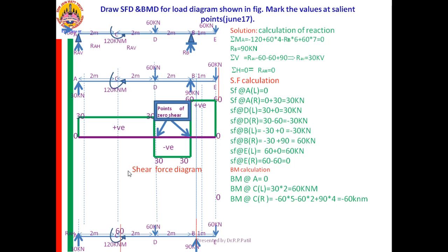Okay, bending moment at D I want. As far as possible, I want to avoid the couple. That is why I will take the left part for the calculation. At D I want, but the calculation I am doing by considering the left part.